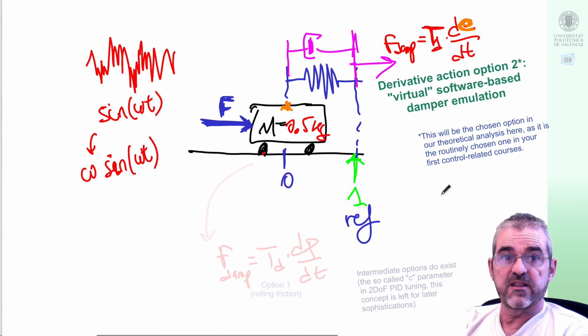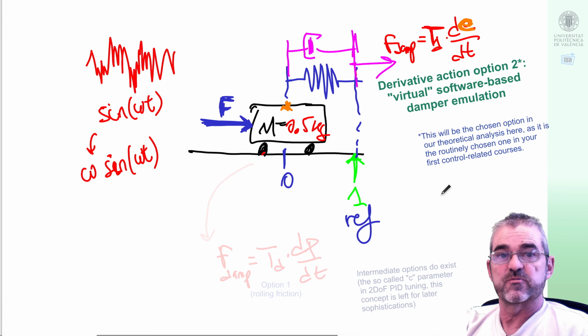Of course, the advantage with respect to mechanical suspension tuning of springs and dampers is that if I do it by software, then changing the damping and spring characteristics can be done just by typing on my keyboard, and I don't need to dismantle my car to change the suspension. But of course, it requires software, sensing and filtering technology that somehow has a greater complication than a passive suspension, let's say. But okay, let's now go into the computation of the closed loop equations.